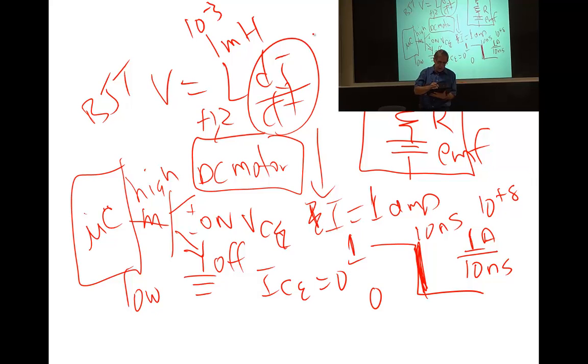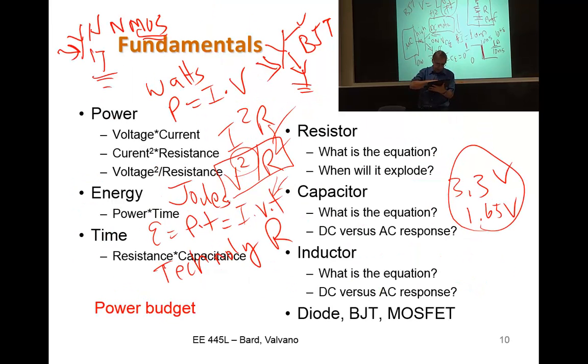And so I just created 1,000,000 volts. To be more realistic, let me make this 10 to the minus 6, a microhenry, which is more typical. We're going to get 100, 200, 300, 1,000 volts right here. That's a problem. We'll fix it. We won't let you blow up each other's stuff.